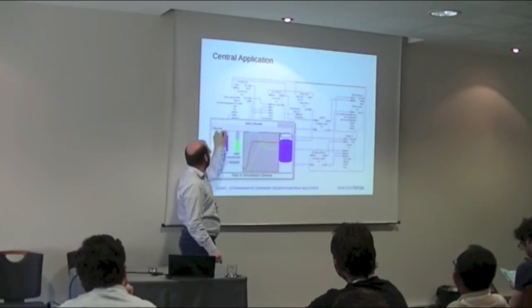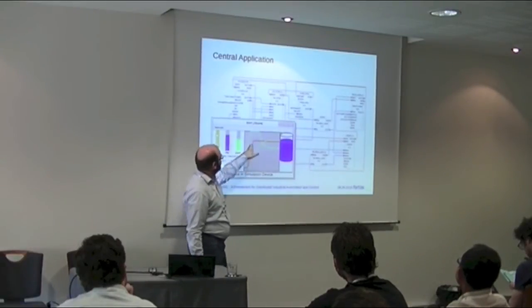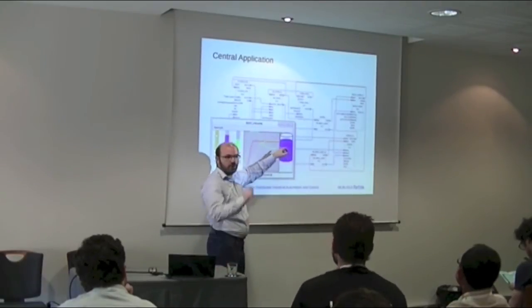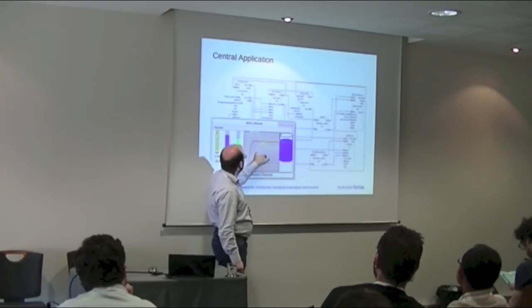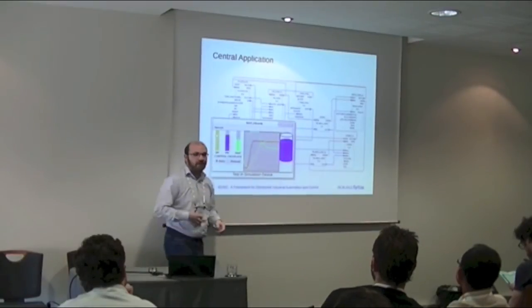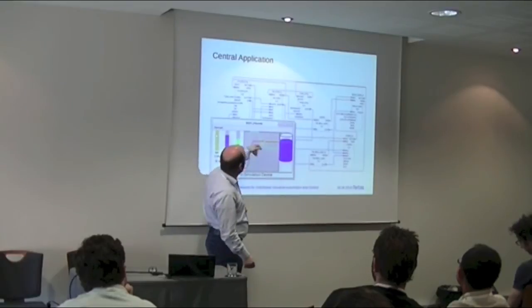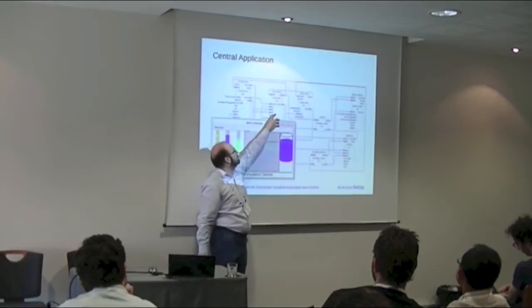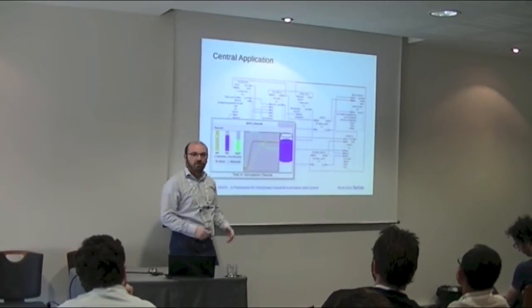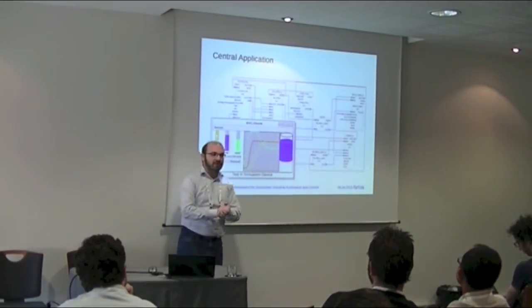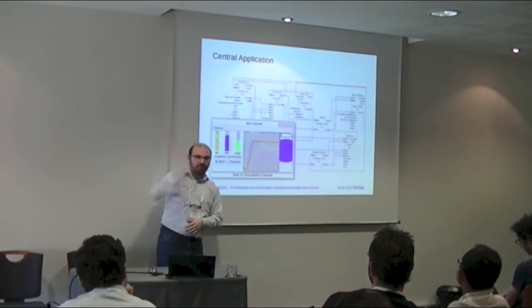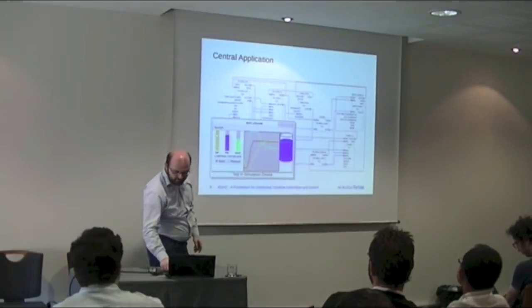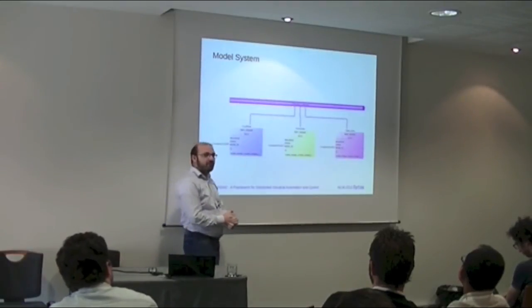So the red line is the yellow here. So this is what I would like to have as a set point. You see here the motion of the valve, so if it's opening or closing. And the yellow one is the current value of the tank. You see, this is already quite good. We have some small error, so maybe I have to adjust the parameters of my PID control a little bit more. But for the first step, it's quite okay. So it's working. It's not exaggerating. We have no overflow of the tank. Okay, that's fine. So in the next step, we can model our system.